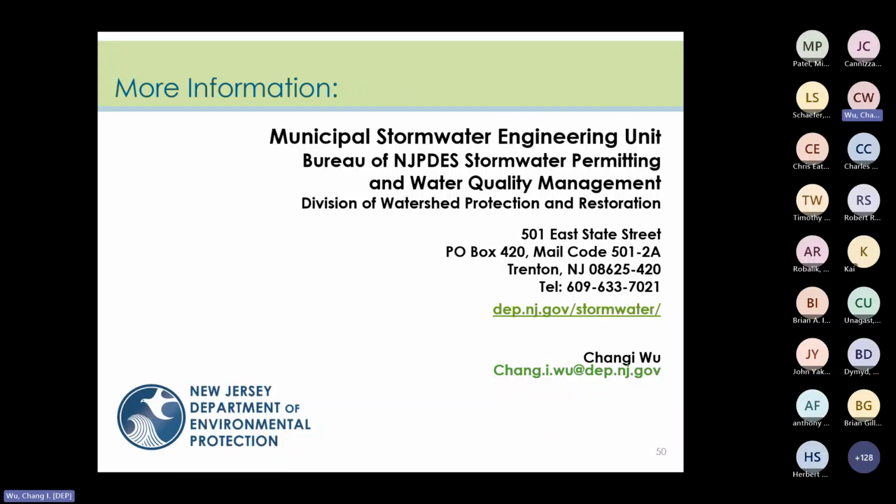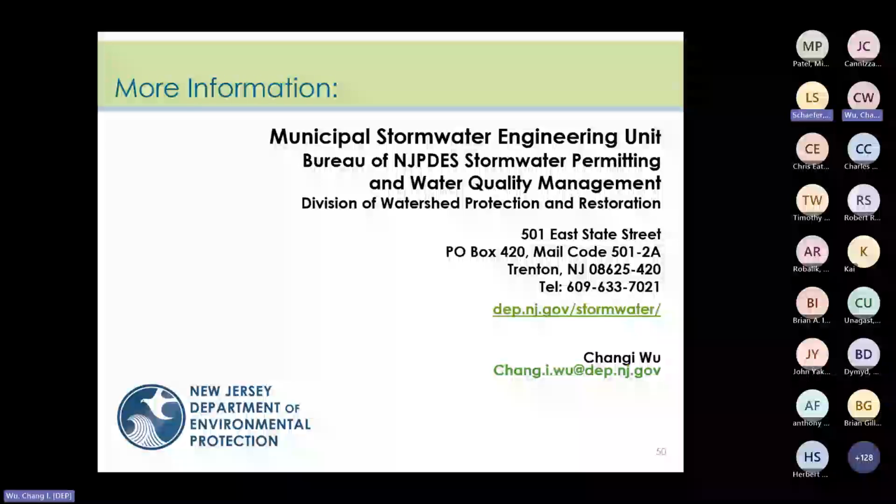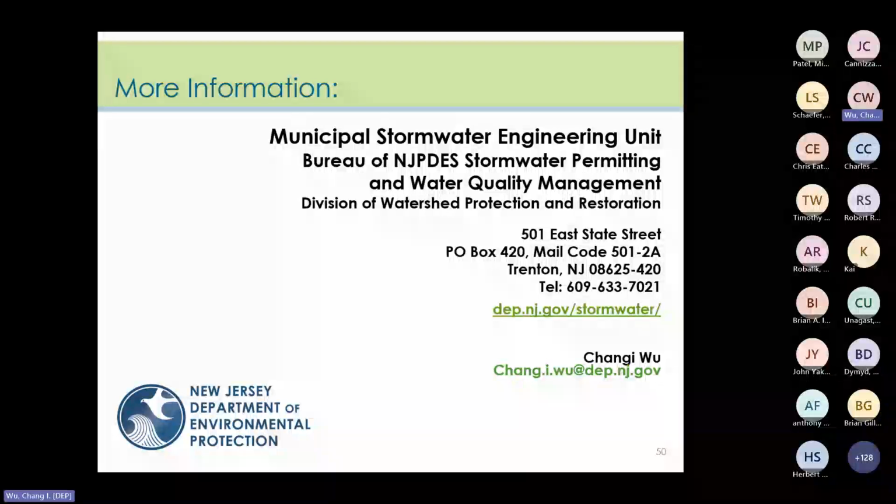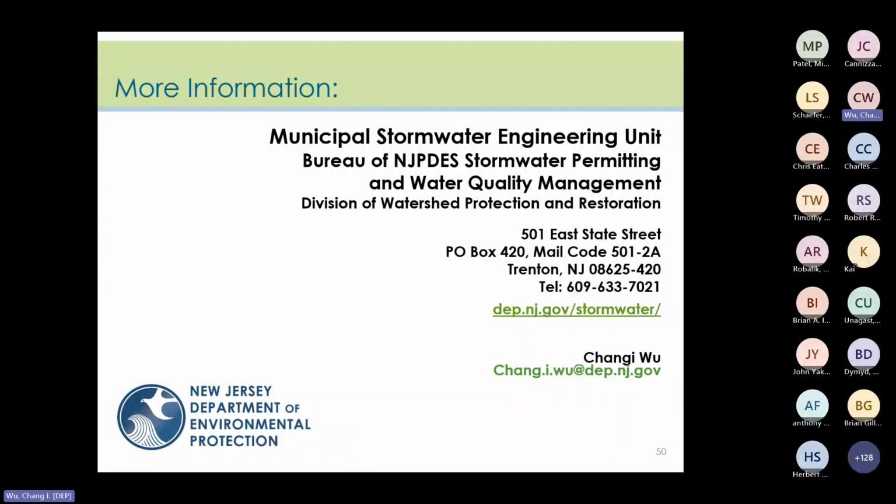And I saw another question related to the heavy metal. You already addressed that, but I want to emphasize it's not the whole site, the historical fill site, that's exempt from groundwater recharge. If an area will produce heavy metal contamination in the runoff, you cannot do the recharge.